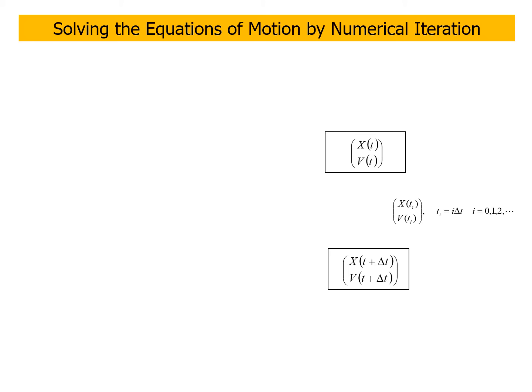Now, solving the equations of motion, we have two ways, either through the initial value problem or the boundary value problem. The initial value problem is I will give you initial conditions, you do iterations, and you get another iteration, and then another iteration, and you get the points as the trajectory is moving, point by point. So if we start with A X equals B, I know A, because A is the mass matrix.